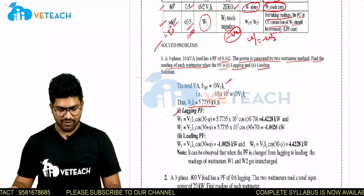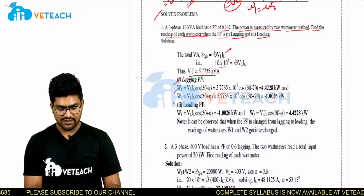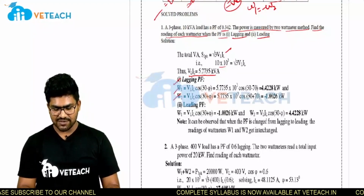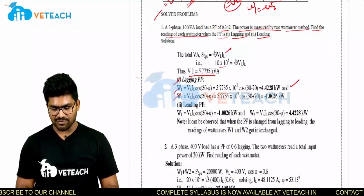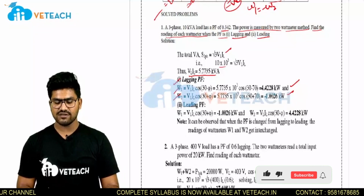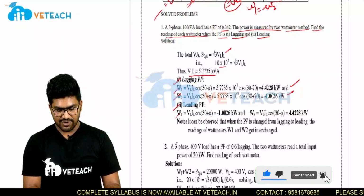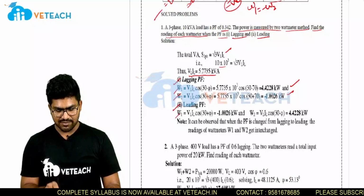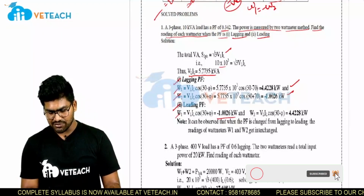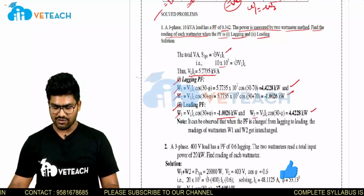If it is a lagging power factor, W1 reads VL IL cos(30 minus 70), W2 reads VL IL cos(30 plus 70). Substituting these values, W1 is 4.42 kilowatt and W2 is minus 1 kilowatt. For leading power factor, W1 reads VL IL cos(30 plus 70), so it will be minus 1 kilowatt, and W2 reads 4.42 kilowatt.